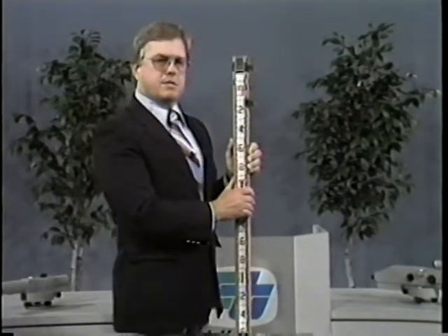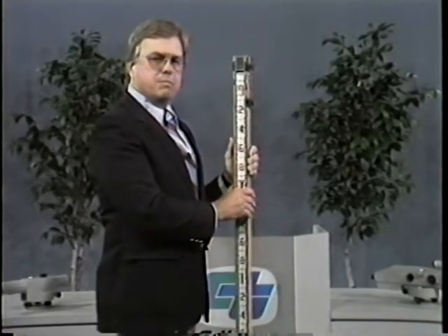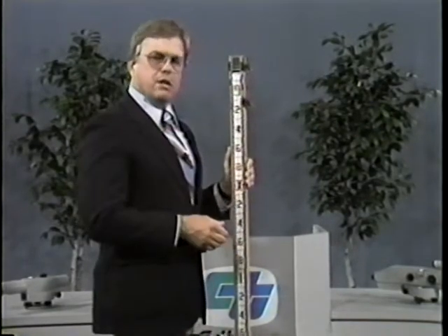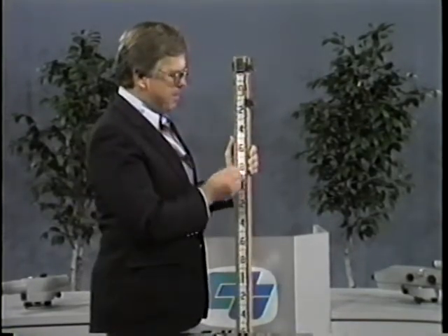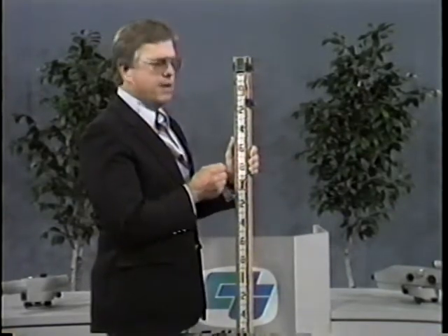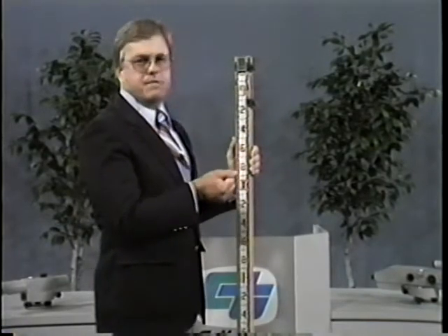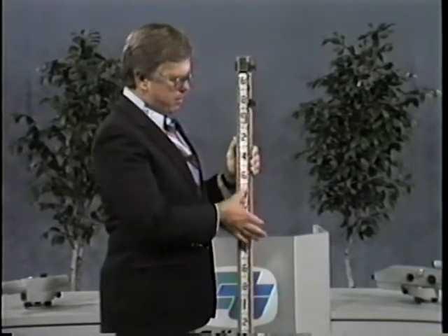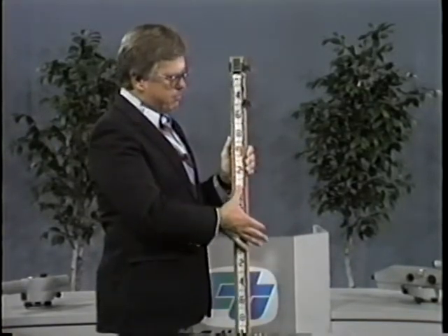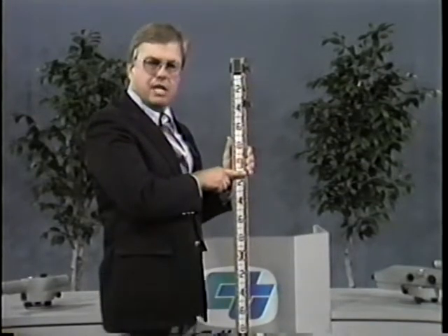Now what this does is facilitate setting an elevation in the rod. When the instrument sets up and reads the elevation on this rod set on the benchmark, the instrument man can tell the rod person what the elevation is. Let's say, for example, that the rod reading is 109 feet and then 1/10. So when the line of sight was down here, this tape would be rotated to read 910 right here on the tape.